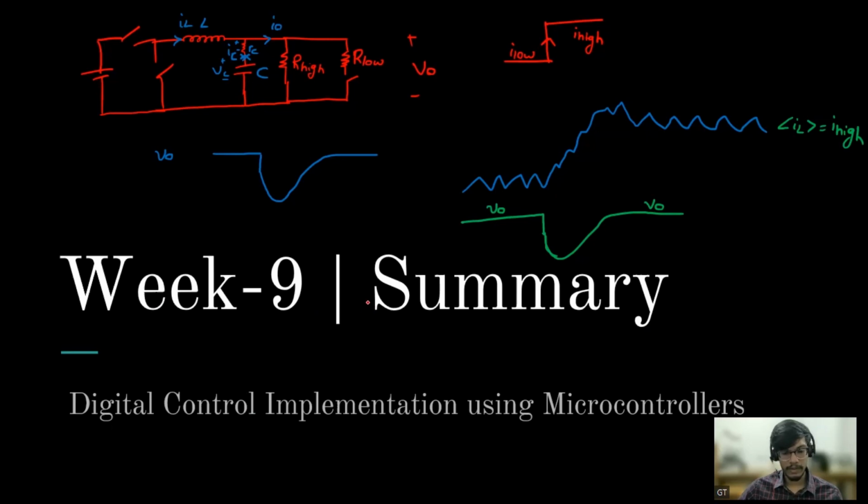In the lecture, sir is saying that where the V naught has fallen, at that point he is maintaining the reference. I'm not able to understand. Are you talking about the output capacitor having a resistor divider here? Are you talking about this?